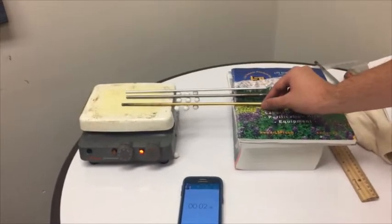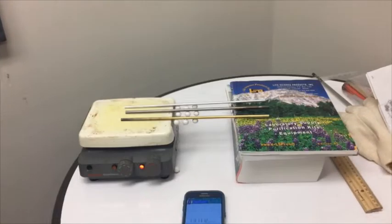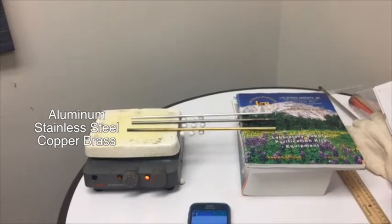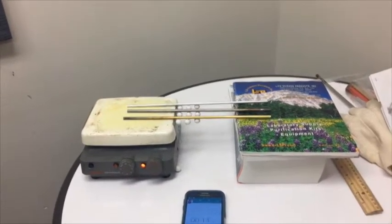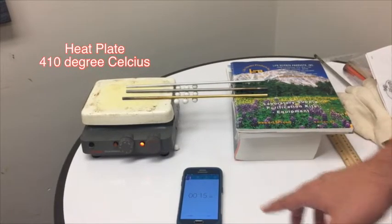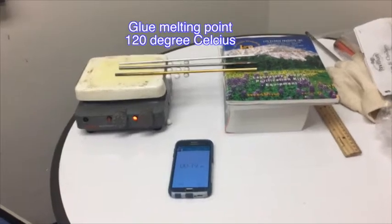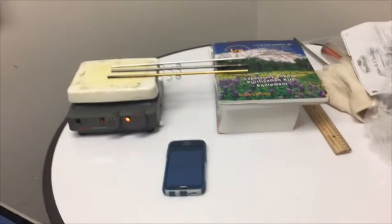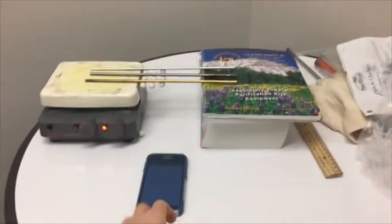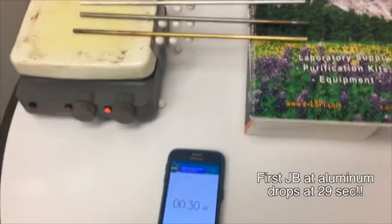In order to demonstrate the effect of different thermal diffusivities, we glued 3 jawbreakers to the outside of rods of 3 different materials: aluminum, copper, and stainless steel. We placed the ends of all the rods on a hot plate that was heated up to about 410 degrees Celsius. Since the glue used to attach the jawbreakers to the rods melts at about 100 degrees Celsius, we knew that the first jawbreaker on the rod with the highest thermal diffusivity would reach 100 degrees the fastest, melting the glue and causing the jawbreaker to drop.